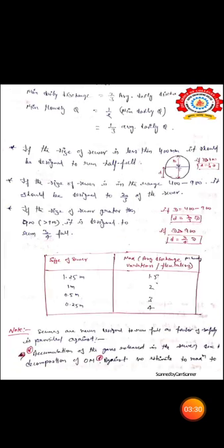The variation of the sewage is shown in the graph, where Qw is the discharge of the water and Qs is the discharge of the sewage. At a particular time, the discharge of water is always greater than the discharge of sewage. If the data about the discharge is not given, then we take the maximum daily discharge as 2 times the average daily discharge, and the maximum hourly discharge as 3 times the average daily discharge. All the discharges are computed by these relationships.